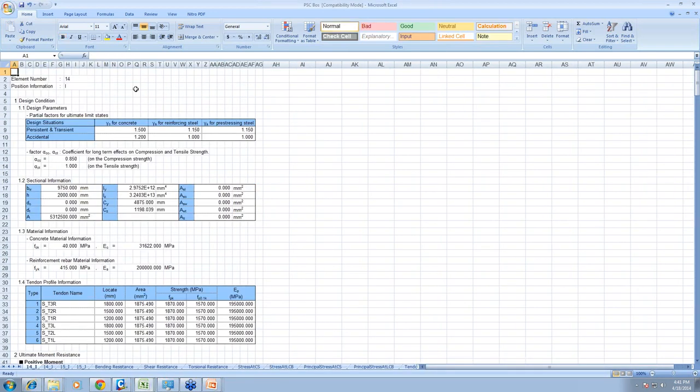Modi sir, actually if you want to have a temporary bearing in between, what you can do is this: a temporary bearing means it will be there for some stage. In the next stage it will be deactivated, because it's a temporary bearing, right? So we activate a particular boundary condition in one stage, and in the subsequent stages we deactivate that boundary condition.